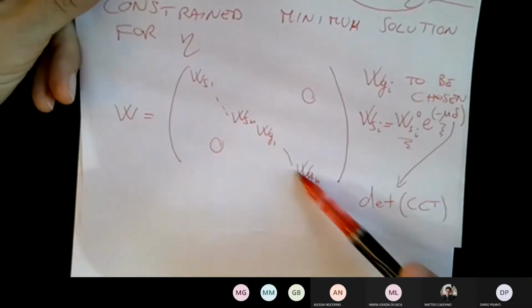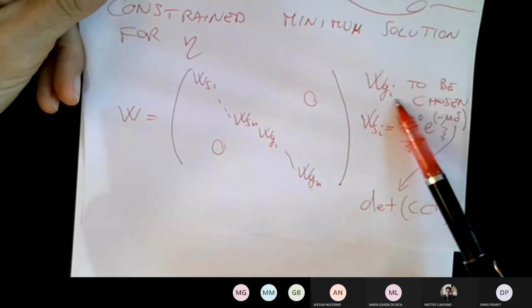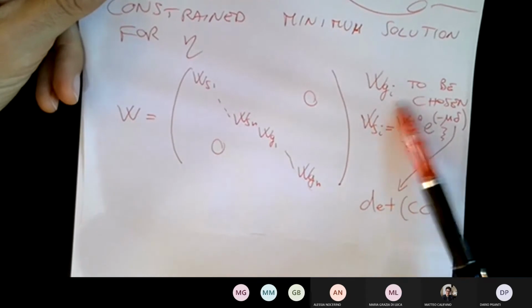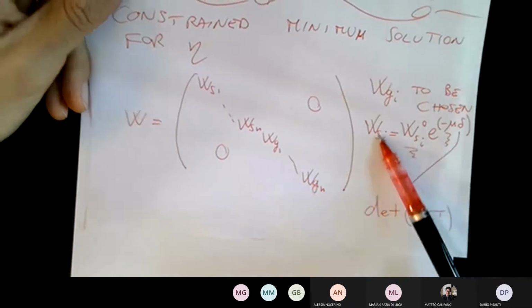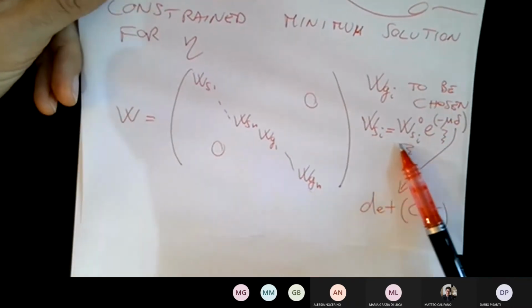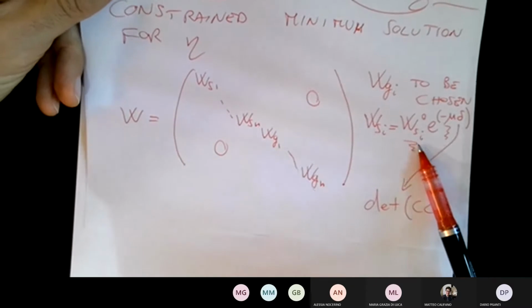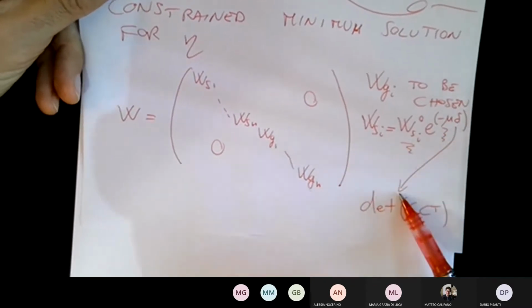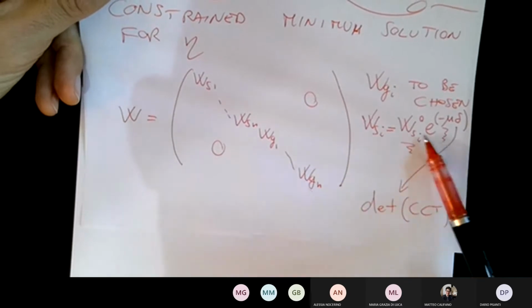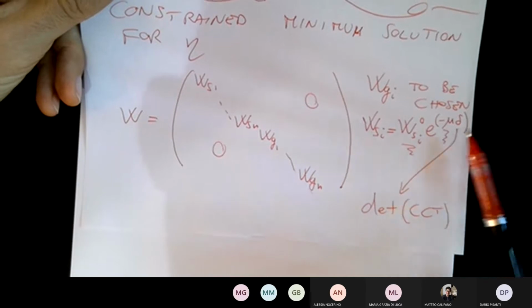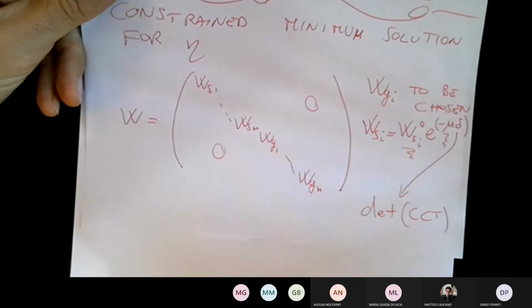So basically the problem that I want to define, and let's refresh for a second the weights in this matrix. The WGs are all scalars. These are the weights for the gimbals, can be chosen to be some values that we keep constant, while we're suggesting to weigh more the use of the wheels, so in case they can actually spin up or down as a function of how close we are to being singular. In other words, how close this delta is to 0. As you can see, you get the maximum of this exponential where delta is 0.